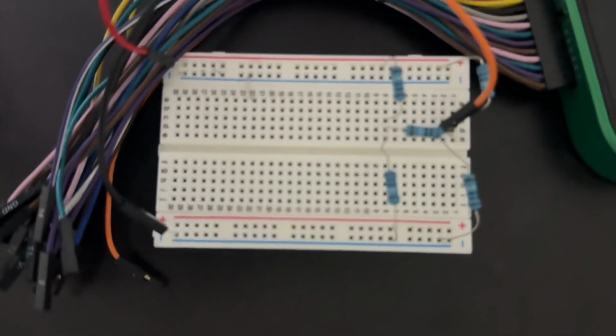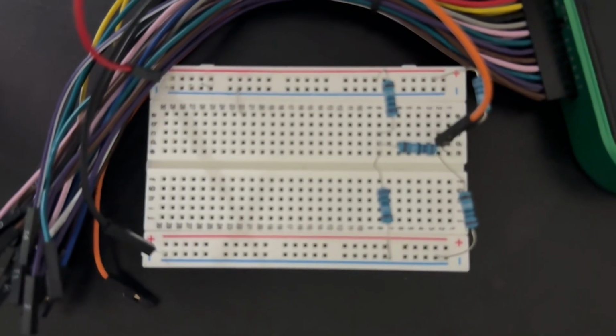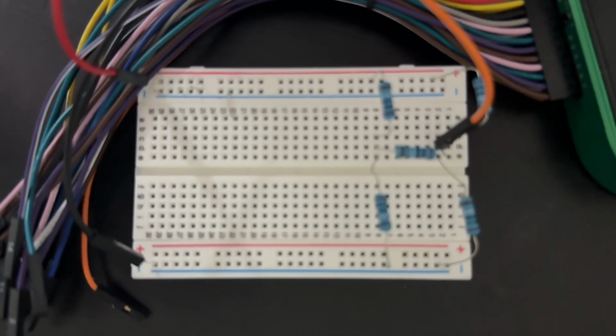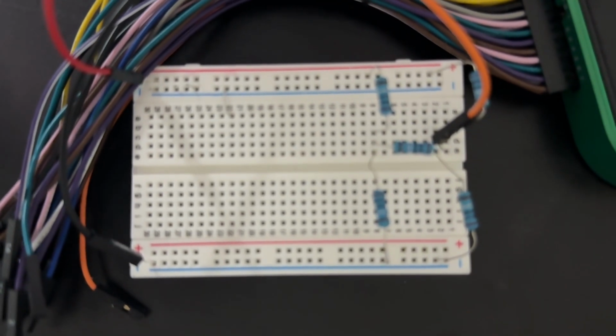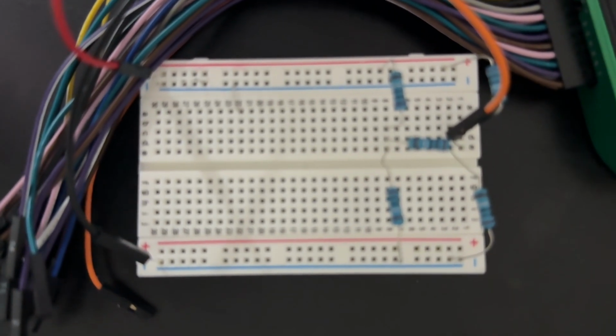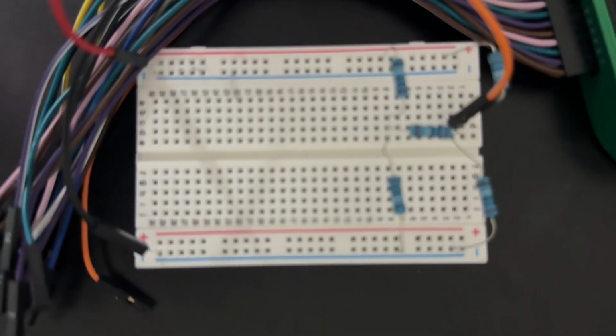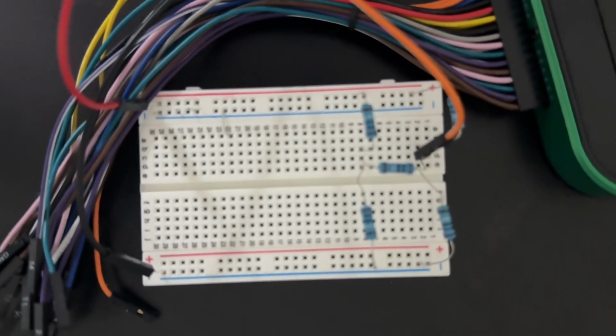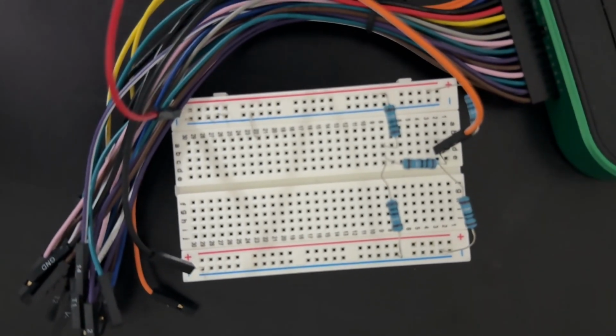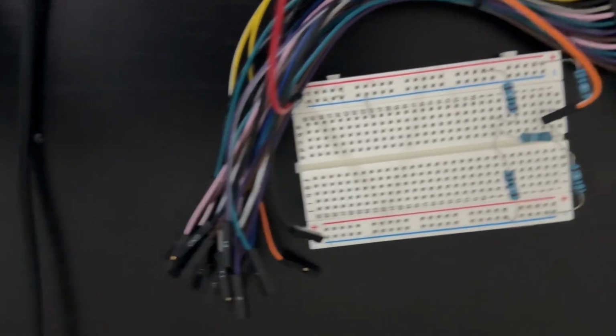There you go. So that's the top right corner, the 1K ohm and the 470 ohms on the left. These are actually all 470 ohm resistors, so I guess the top left is actually correct, but the rest are all wrong. But this is how you'd want to wire it up to get your voltage and amperage, and this is how you take the measurements in WaveForms.